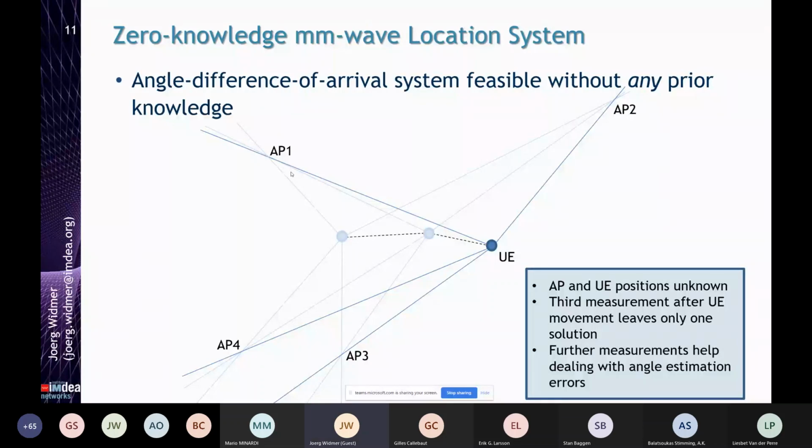And so if we take many such steps and we want an estimate that has the condition that the access point positions are always fixed, and the UE trajectory is not just completely random all over the place, but a sequence that makes sense over time, like a smooth trajectory, then we can actually formulate this as a geometric problem and solve it. And this is a very hard problem to solve. It sort of requires higher order trigonometric polynomials and so on. But it is solvable, right?